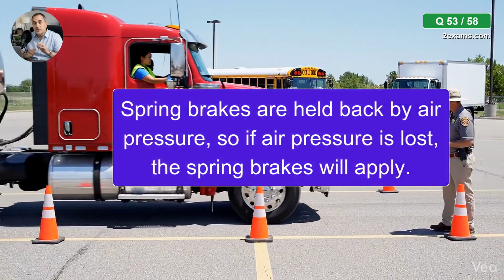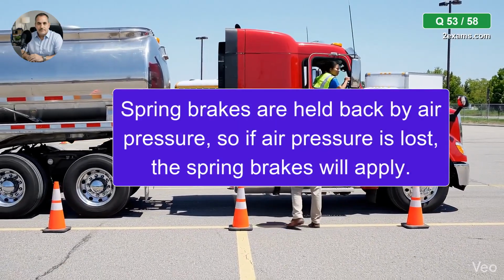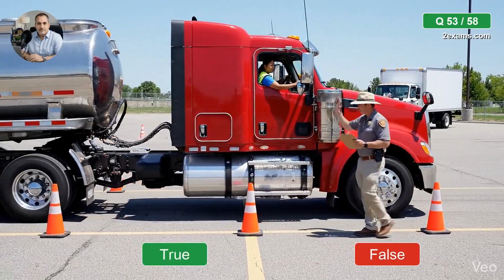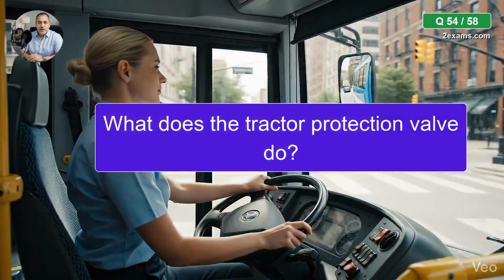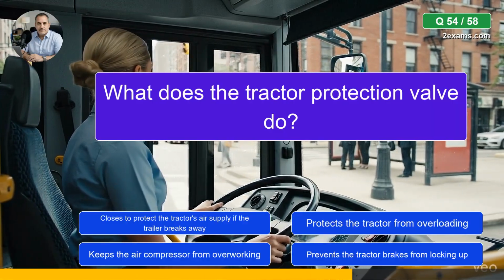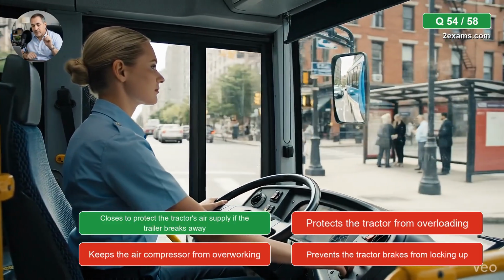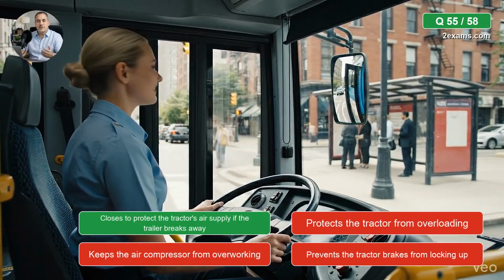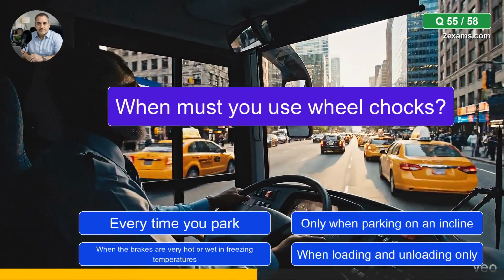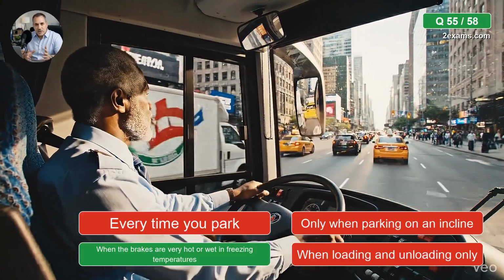Spring brakes are held back by air pressure, so if air pressure is lost, the spring brakes will apply. The correct answer is, true. What does the tractor protection valve do? The correct answer is, closes to protect the tractor's air supply if the trailer breaks away. When must you use wheel chocks? The correct answer is, when the brakes are very hot or wet in freezing temperatures.